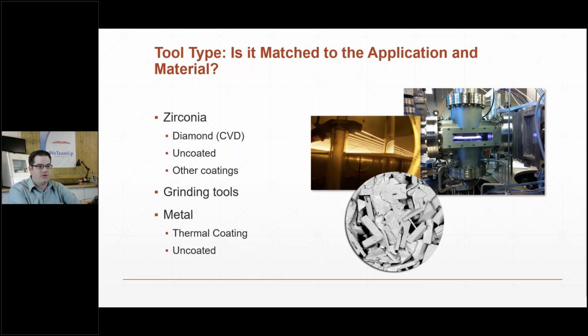It's a nanocrystalline diamond directly on the tool, and that's done in some really highly space-age precise equipment, and it's really the only way to get a real diamond coating on carbide. And then if you really want to get into the nuances, there are differences in the CVD coatings, but if you want to know about that, we can talk about it offline. That's another half an hour conversation.